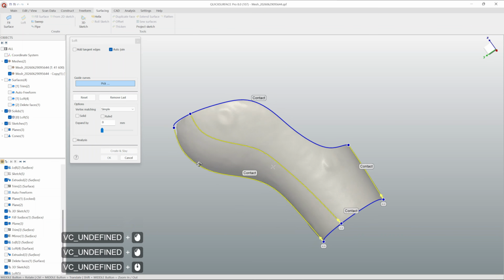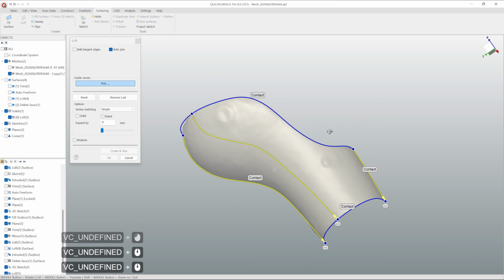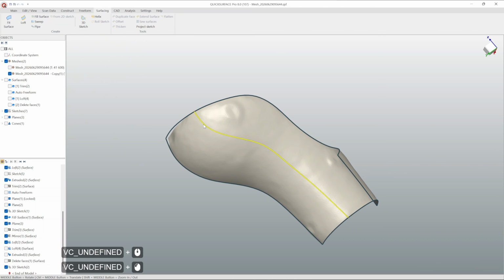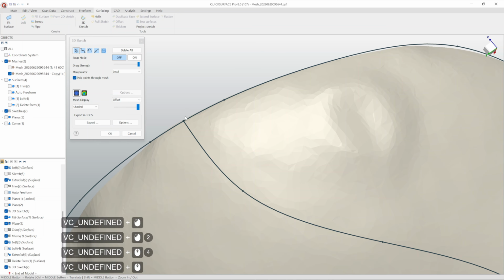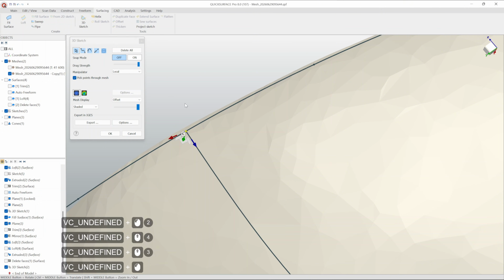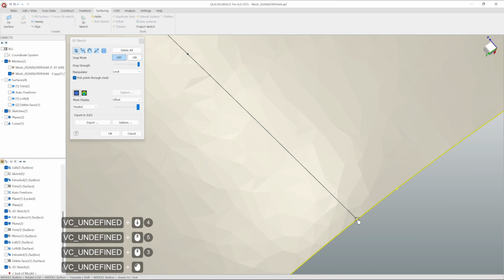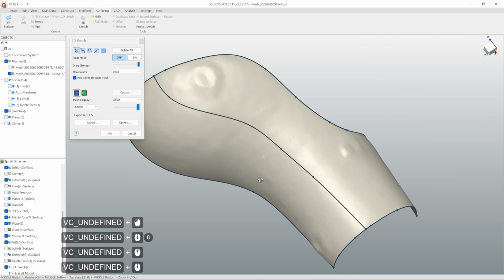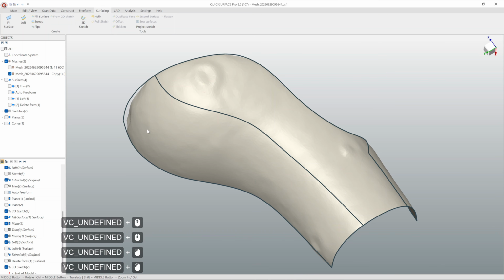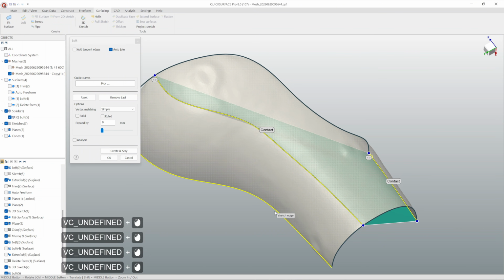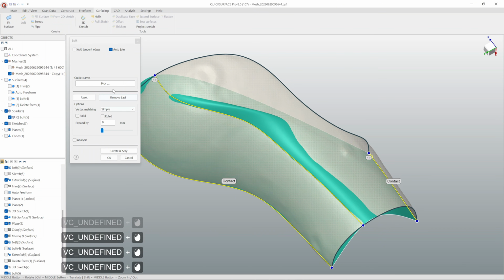Okay, so in this case, it starts to create already a self-intersecting surface, and this is the reason why it is failing. Of course, you have to check always if we have a snap to our guide curves, but in most cases when it starts to fail, it's just because result of this loft creates self-intersection.